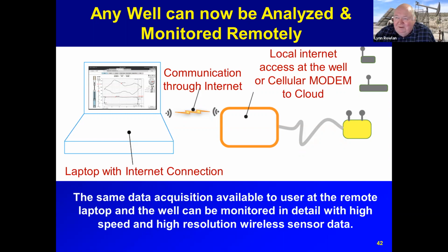You need to understand that you might see some things different than in a vertical well, because in fact, I've seen flow shots on plunger wells where they shot down the tubing and the well made maybe 1 or 2 barrels a day of liquid, and the horizontal well was slightly tilted up toward the end of the horizontal, the toe. And the guy shot all the way out to the end of the well, because the liquid's on the bottom and the gas is on top. So that's a little bit different than a vertical well, but yes, you can absolutely use our equipment on horizontal wells without any trouble.